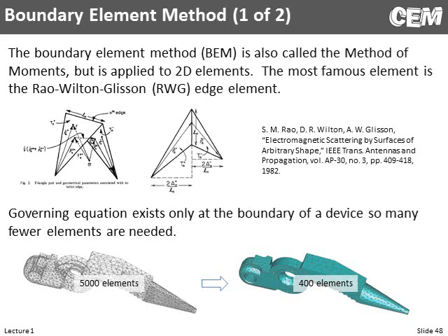The classic example is a sphere that has very little surface area compared to its volume. That's why they store cryogenic things in round tubs. It loses less heat. So if you were to model a sphere, boundary element is ideal for that because there are very few elements around the surface. Whereas finite element, you'd have to resolve it throughout the volume.